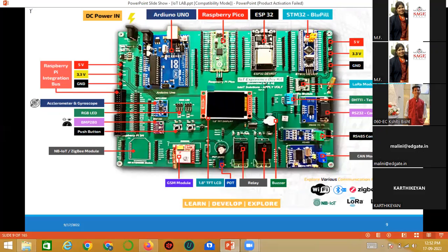Then what is the essential thing for IoT communication? The essential thing is connectivity. Connectivity in the sense of Bluetooth Low Energy, Wi-Fi, LoRa, and GSM. Different wireless connectivities are there. So using ESP32, there is onboard Bluetooth low energy communication. The difference between Bluetooth communication and Bluetooth low energy is the power consumption, because power is important in terms of